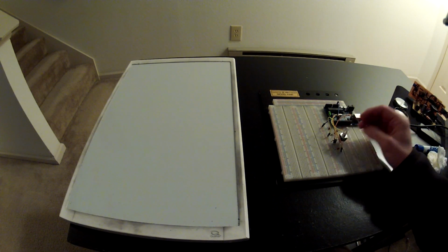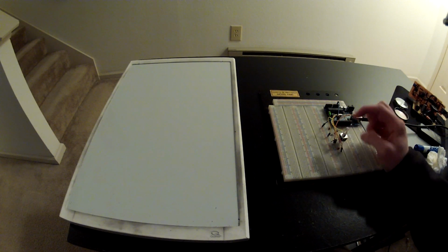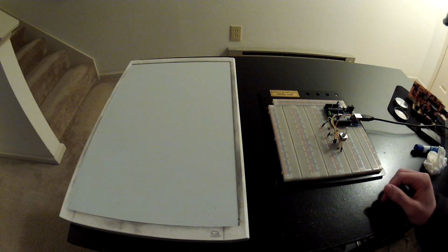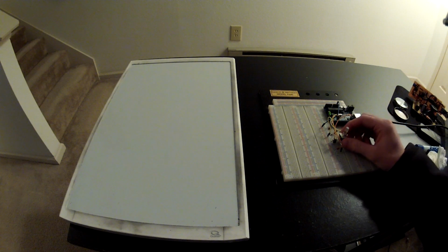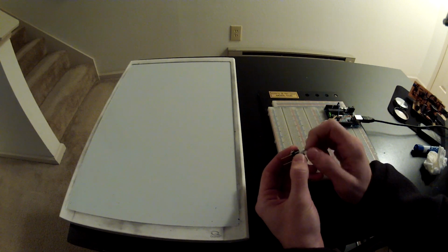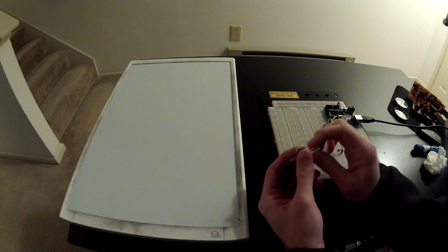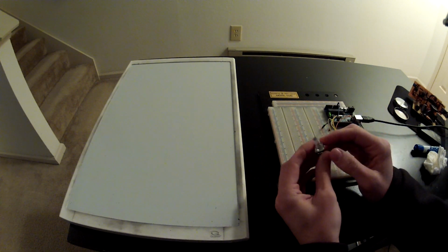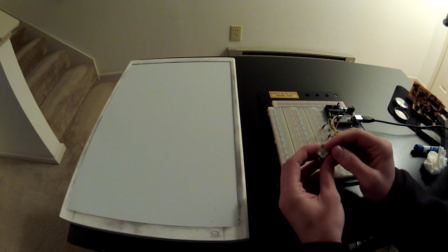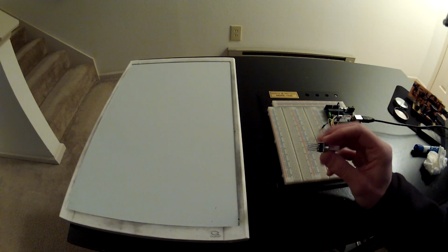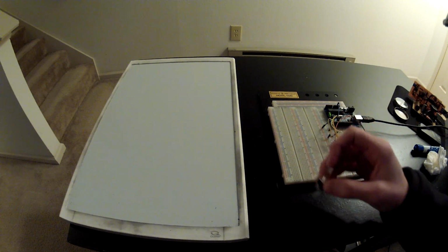Now, I'm not going to really get into the details of the pros and cons between using a rotary encoder and a potentiometer, because I'm assuming that if you're watching this video, you've already made that decision. But real quick, a rotary encoder just spins forever, okay? It gives you incremental position feedback, meaning you don't actually know exactly where it is. It's not absolute. It only gives you the position in relation to where you were previously, which is why it's called an incremental encoder, and it provides digital data to the microcontroller.